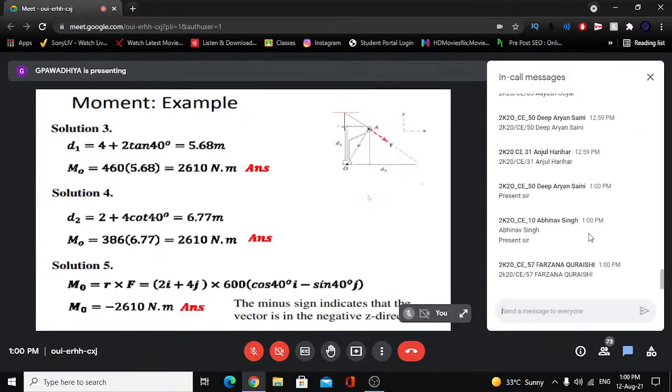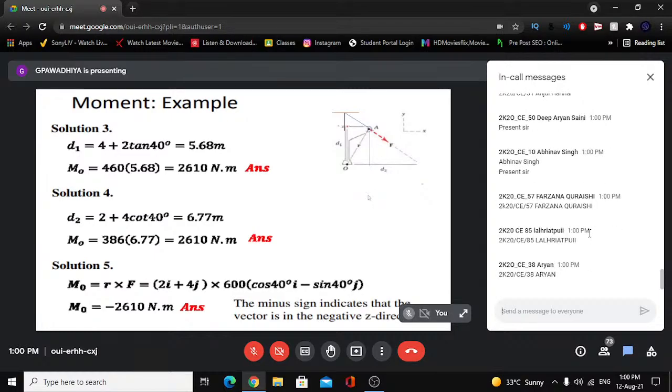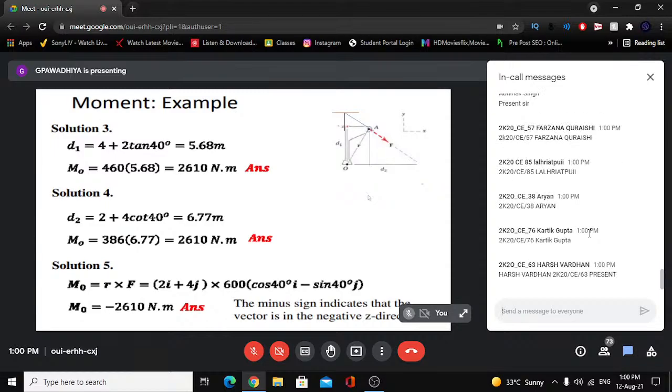When we want to draw a vector in 2D, if it is the head, then we draw a circle, and at the center of this circle we draw a dot that represents the head of the vector. So in this case it will be the tail of the vector seen from this side in this 2D plane. This is why R cross F is very important. If you properly represent these vectors R and F, you will get the moment vector with the proper sign also.